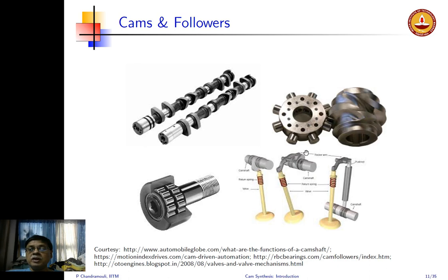Or you can have a rocker arm. The old style engines used to have a rocker arm. So the cam will actually actuate the rocker arm, which is basically pivoted here. So this is another link, an intermediate link. And this link is in contact with the valve, which actually pushes. So you have this oscillating back and forth. So the cam moves it up, and then this rocker basically rocks, as it's called a rocker arm. It rocks about this pivot here. So you have an additional part. So that has been eliminated in most modern engines.